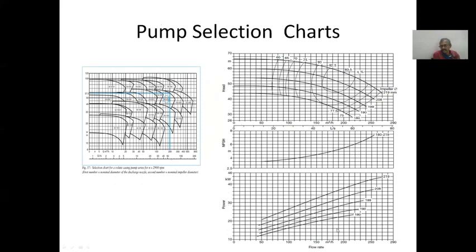And finally, power for different impeller diameters, what is the power. So this is how it is given. So what you do is, you again use your discharge rate here and go up and select. You go very near here, along this is the maximum efficiency path.